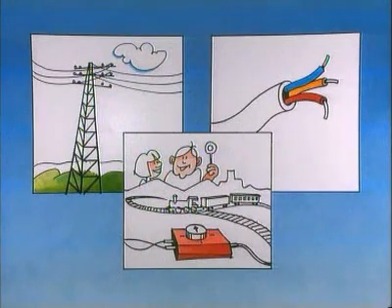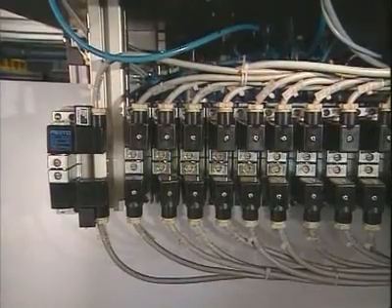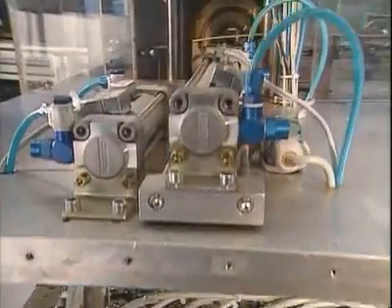Other protective measures. High voltage cables are laid in such a way that no contact with them is possible, or so that no voltage can jump across. And current-carrying lines are insulated. And finally, low voltages are used wherever possible.